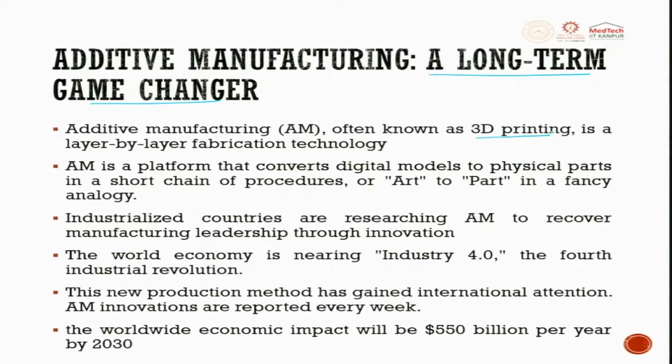Additive manufacturing, often known as 3D printing, is a layer by layer fabrication technology. So, here we are trying to add material layer by layer, or space by space, or island by island. You join them to form a final part. Here the energy will be reduced to a large extent in manufacturing. It is not only the energy, but also the use of coolant and pollutants which are involved in the process are also reduced.